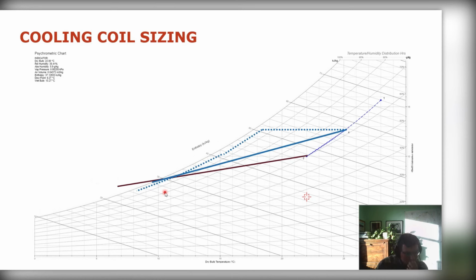Okay, I think there's a question there from Hassan. Does the debris in the air play any role in our calculations? Generally speaking, no. I would only say that if you have an extreme amount, so if you have a huge amount of say solid particles like sand or something like that, and then you're heating up or cooling down, then you maybe want to start thinking about what's the change by mass.